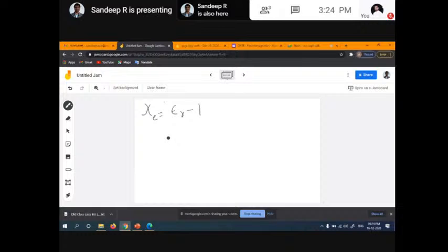Let me write another important equation, which is the continuity equation. The principle of charge conservation, which is the basis of Kirchhoff's current law, is stated in terms of the continuity equation: del dot J, the divergence of J, is equal to minus dou rho V by dou t, or del dot J plus dou rho V by dou t is equal to 0.